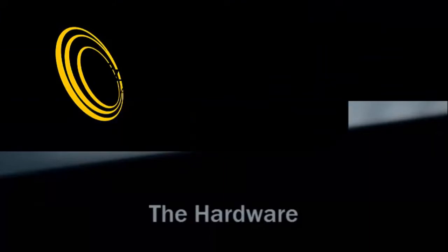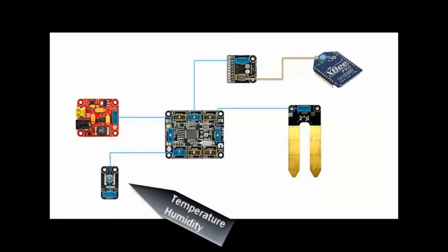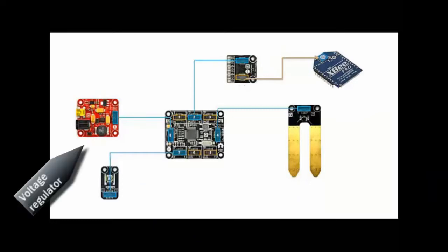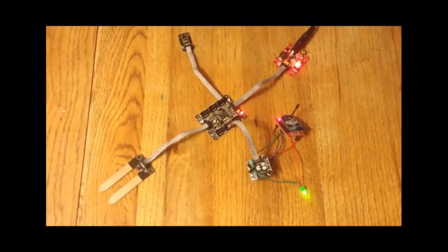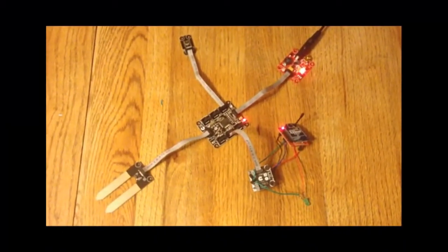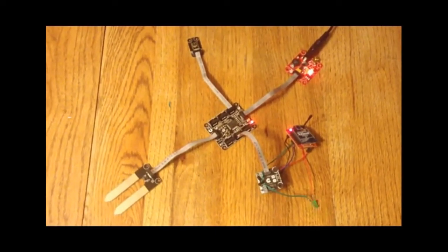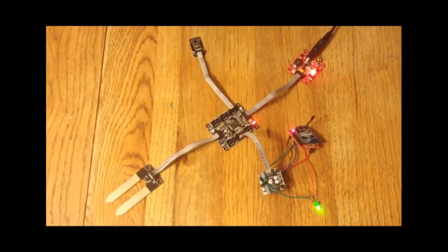The hardware connections. As a microcontroller, we used a Fez Cerberus board, an extender adapter to connect the transceiver XP module, a moisture sensor, the temperature and humidity sensor and the voltage regulator for the whole circuit. Once we did the connections and loaded the code in the microcontroller, the circuit is connected to voltage to see the circuit working. We also added a blinking LED as a visual indicator.